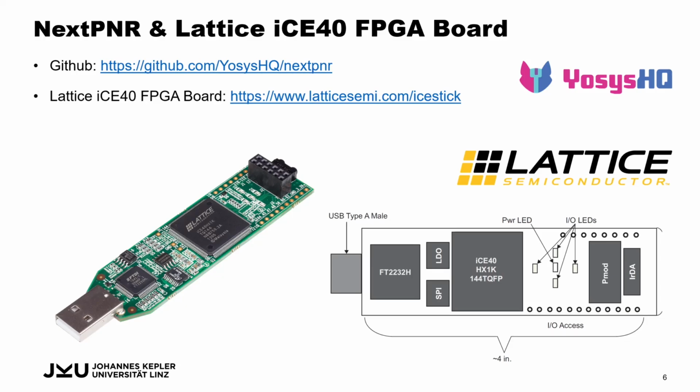But before really making a layout and taping it out, it is a good idea to, for example, flash it on an FPGA and test it there. And when the FPGA design works, then we can say with high probability that we will have a functioning digital layout in the end.